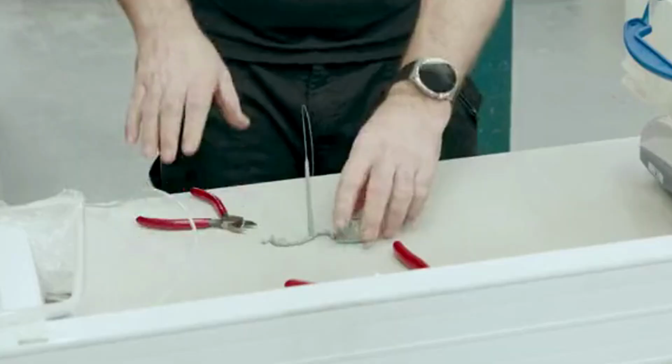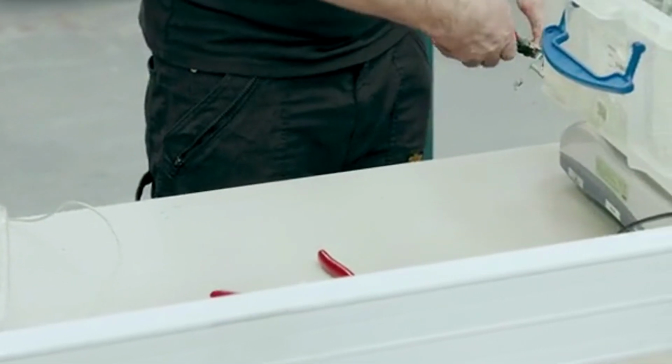Conduct mold strength calculation. The mold needs to withstand high pressure and high temperature during the molding process, so strength calculation must be carried out to ensure the reliability and service life of the mold. Strength calculation includes the strength and stiffness calculation of components such as the cavity, core, and mold plate.